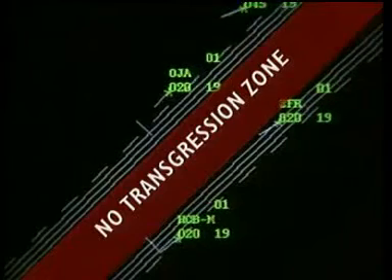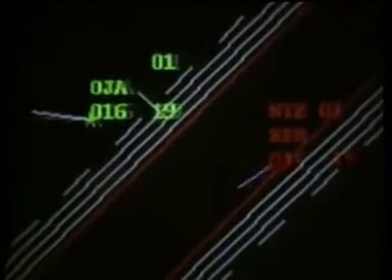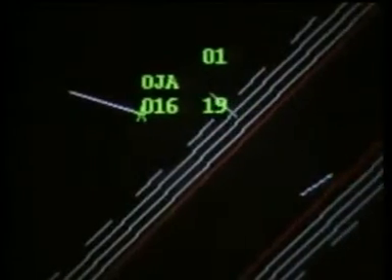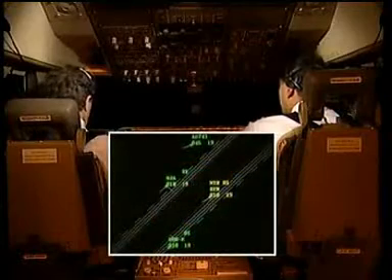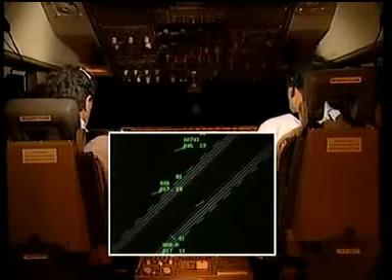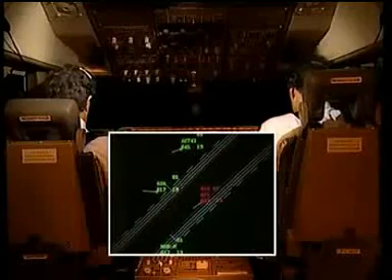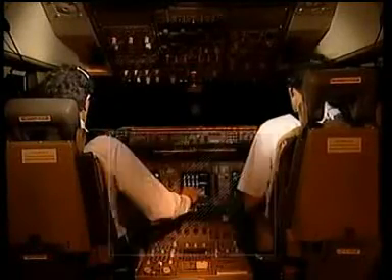The monitor controller must issue breakout instructions to any endangered aircraft on the adjacent approach course when an aircraft penetrates the NTZ. As you saw in the previous scene, a breakout is different to a missed approach because it occurs before an aircraft reaches the decision altitude and, more importantly, requires a different set of procedures than the missed approach.